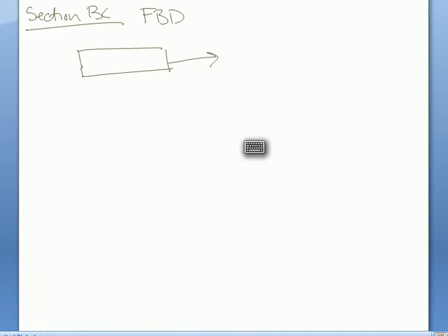We know we've got the 75,000 applied load, making the assumption that the internal force is a tension force. We draw the internal force PBC pointed away from the cut face.